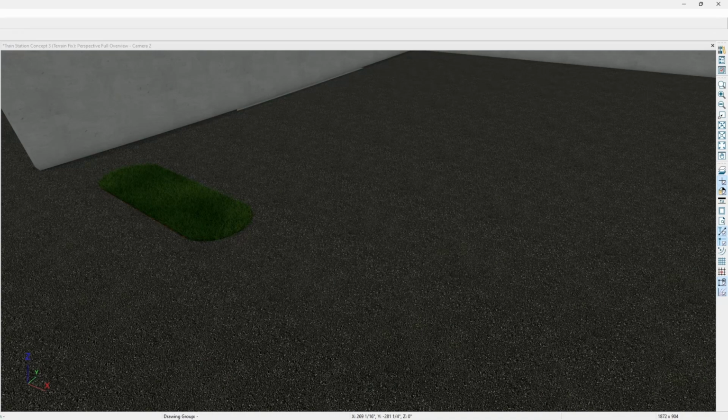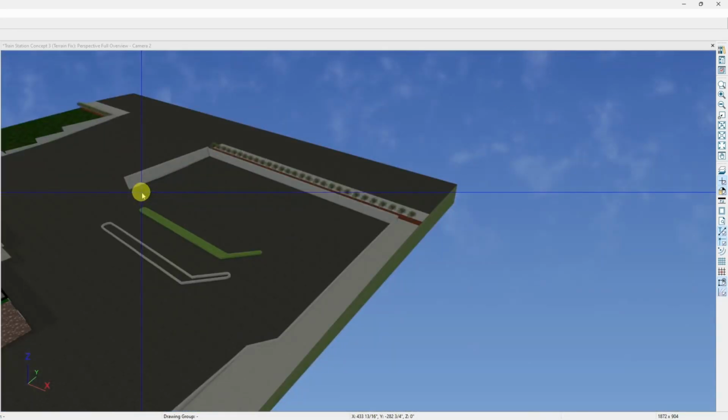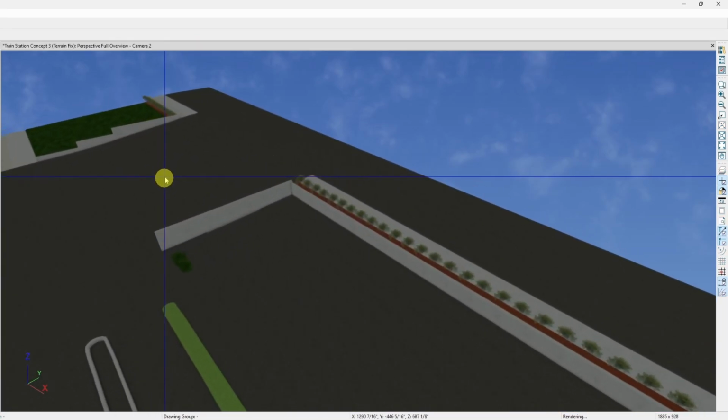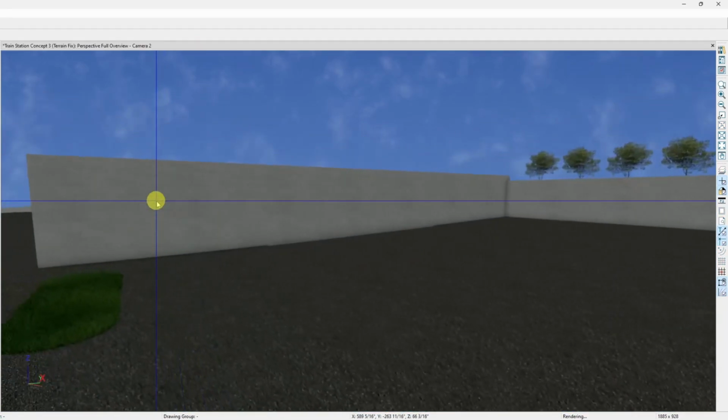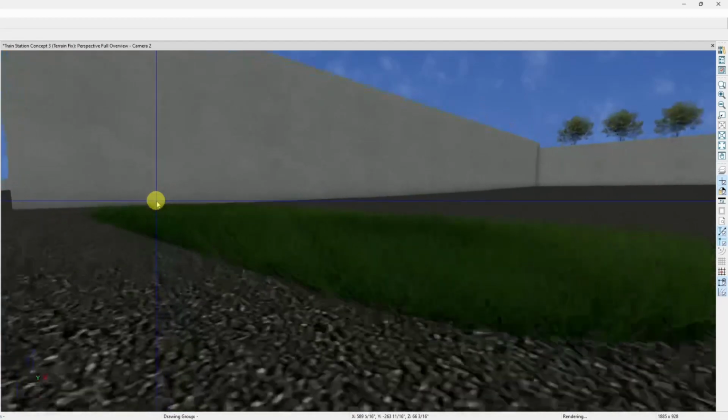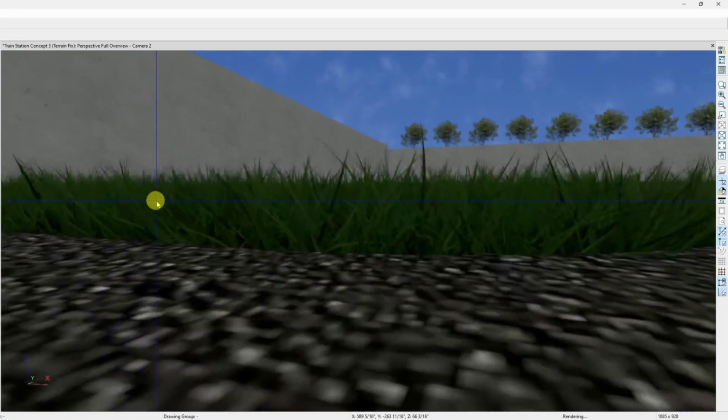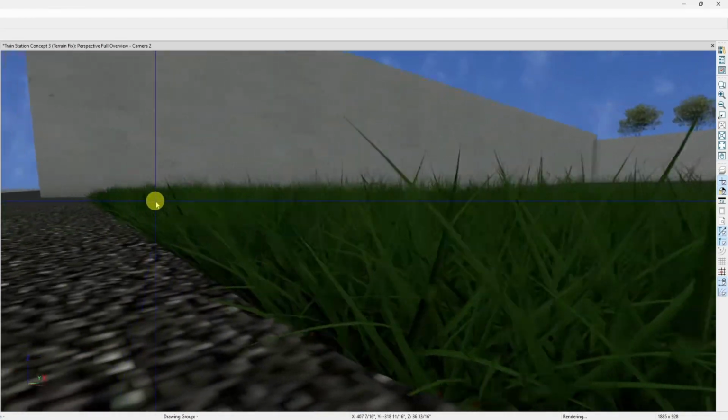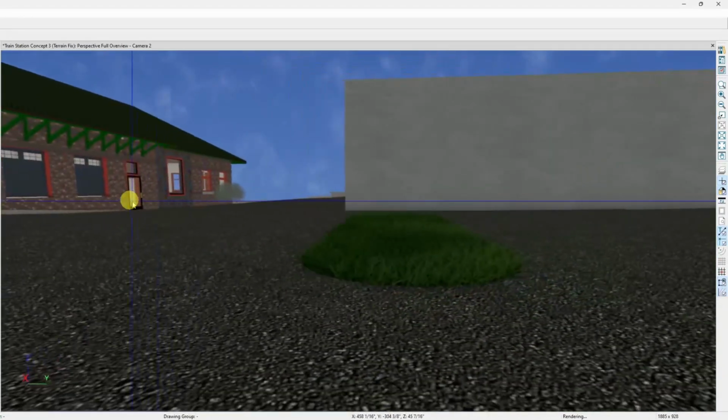Grass. Okay, so what I just learned is you cannot build grass in a hole. You cannot build grass on top of your asphalt. If you want procedural grass, you are going to have to build it. I'm in the wrong drawing trying to zoom. You're going to have to create a hole in your asphalt and then build your procedural grass. If you want the real looking grass like this, then you have to cut a hole to make it happen.